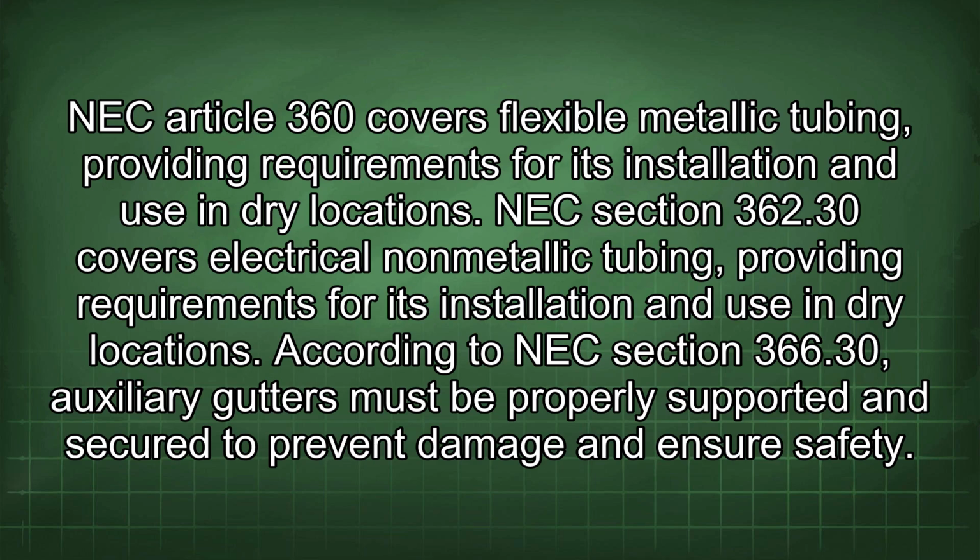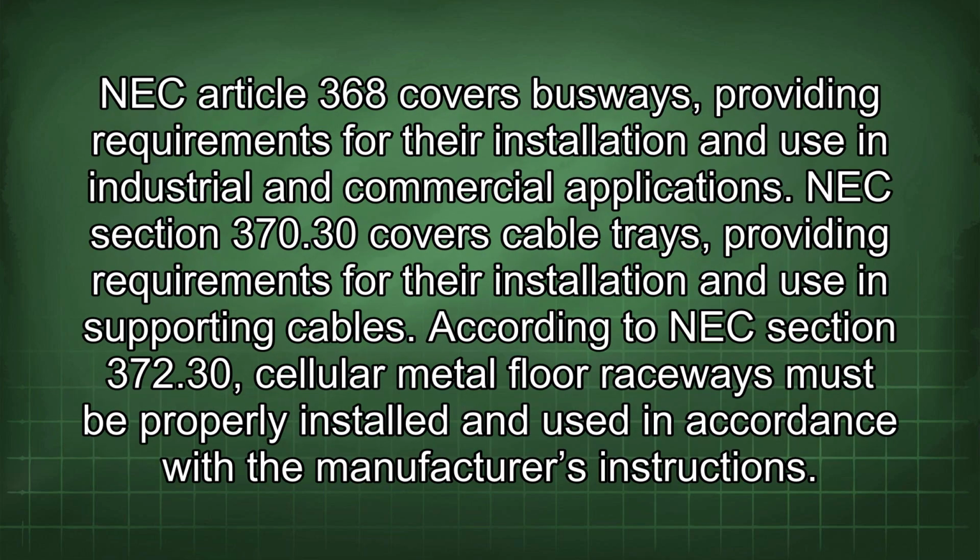According to NEC Section 366.30, auxiliary gutters must be properly supported and secured to prevent damage and ensure safety. NEC Article 368 covers busways, providing requirements for their installation and use in industrial and commercial applications. NEC Section 370.30 covers cable trays, providing requirements for their installation and use in supporting cables. According to NEC Section 372.30, cellular metal floor raceways must be properly installed and used in accordance with the manufacturer's instructions.